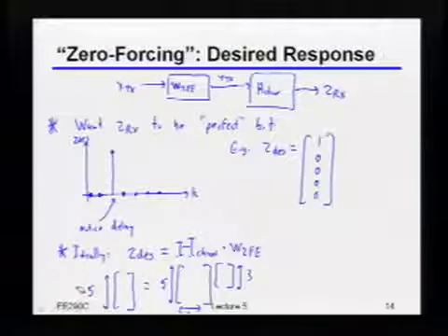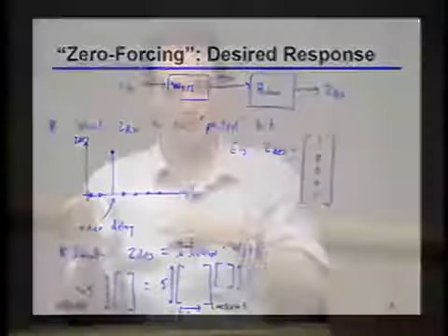If you're talking about estimating what the coefficient values are, then indeed once you're getting to the receiver or sending information back to the transmitter, the way you typically do that is relative, right? So if you know where your cursor is, or you just assume that you are at the right spot, then you figure everything out relative to that cursor. So you'd say, okay, the precursor needs to be this, and the postcursor needs to be that, and so on and so forth. Is there a question in the back?